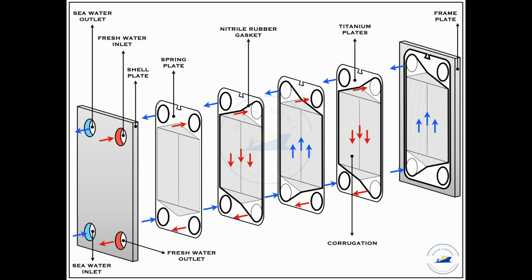During the cleaning of this heat exchanger, it has to be specifically noted that the corrugations are cleaned nicely with either a cleaning aid or with water pressure, and while doing so, the gasket, if to be reused, should not be disturbed. However, most of the manufacturers recommend that if the cleaning is occurring at the specific interval set by the manufacturer, the gasket should be replaced completely.